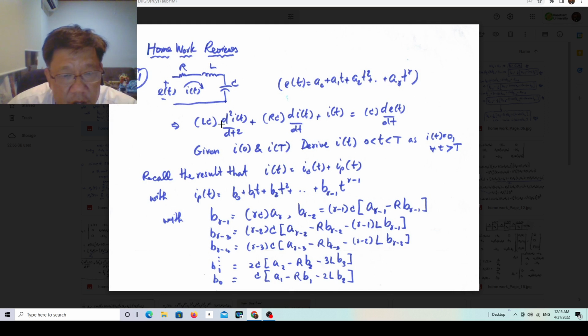I already changed the integral form of the voltage across the capacitor to 1 over D. You might remember the D operator, and this is the resulting second order ordinary differential equation. With this question, we already did it based on the lecture note. We did what we call the initial condition, by giving you I at time 0 and the first order derivative of I at time 0.